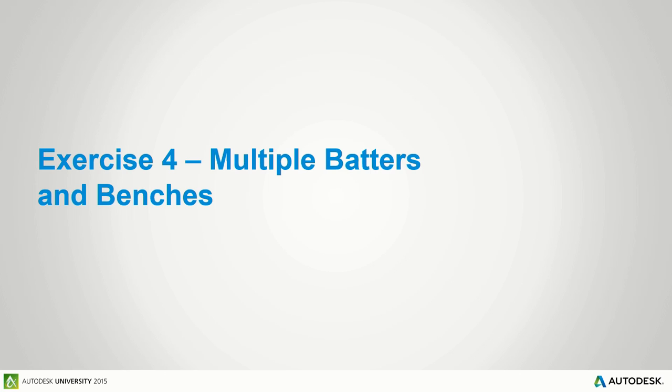Okay, home straight. Exercise 4, multiple batters and benches. This is where we're going to combine everything we've done so far, and we're going to look at the concept. We're going to bring it all together. We're going to use auxiliary corridors, linked alignments, custom sub-assemblies, and, oh, we're just going to use some offset alignments. And we're going to build it all up, and we're going to do a really complex batter slope configuration.